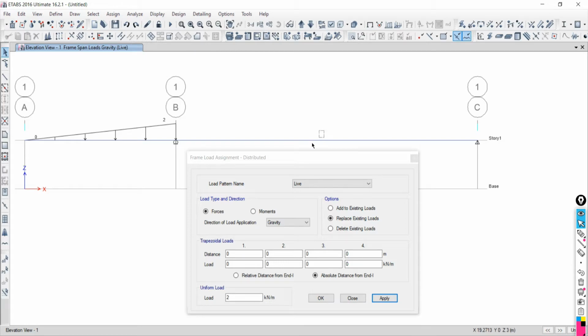Undo. Select the frame. Go with this option, and make it first 0. Now here you may think that it is not 0, that it is 10 meter, then it is going to start at 16 here, so it becomes 26. It is not like that, because it is another frame. These are two separate frames. Now the left hand is I and the right hand is J. It is another frame. Remember.